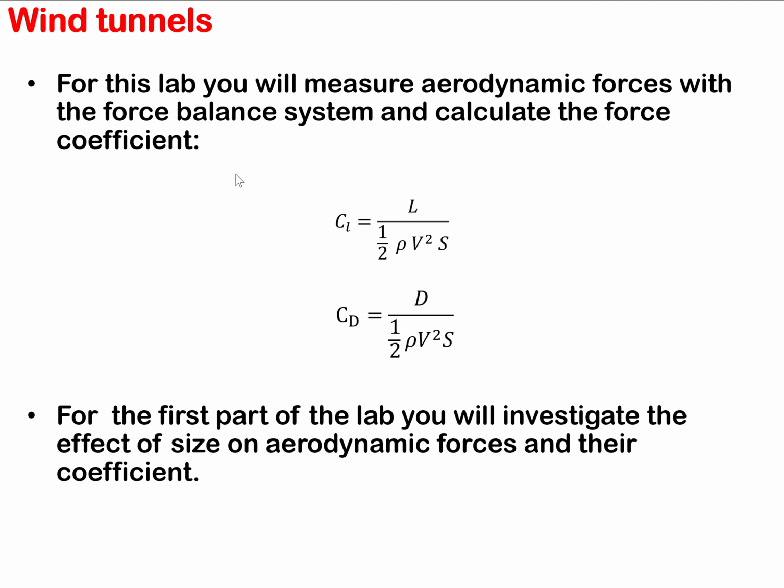Okay. So we have to be able to measure the lift. We have to be able to calculate the surface area. We have to know the density of atmospheric conditions, essentially the surrounding atmosphere specifically, and we have to measure the velocity. Area calculations are simple. You have to get a caliper, ruler, or tape measure, whatever, to calculate the area of your sample.